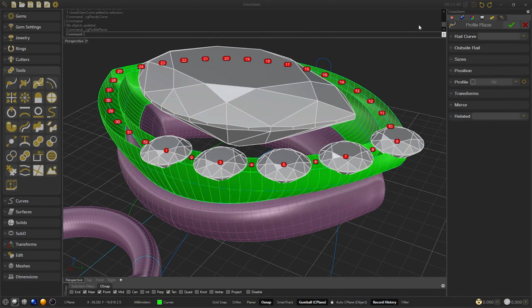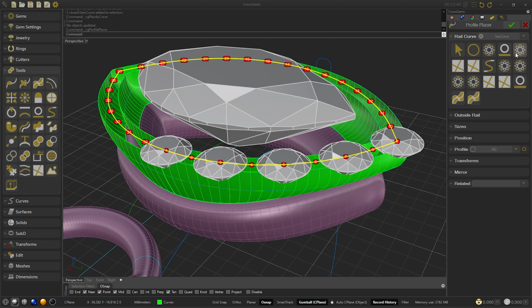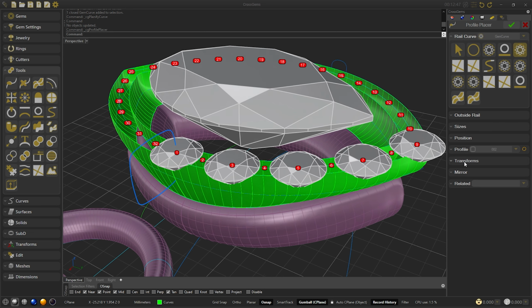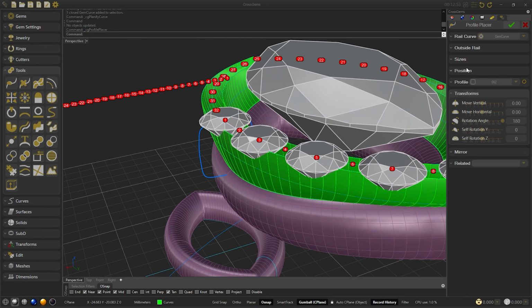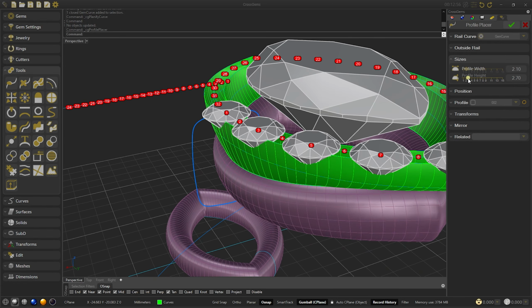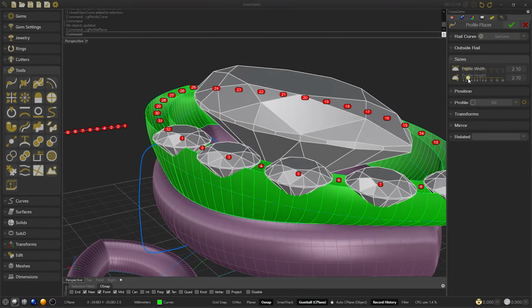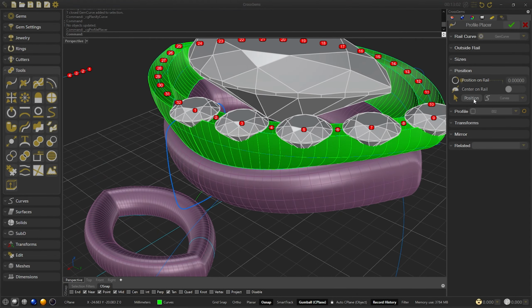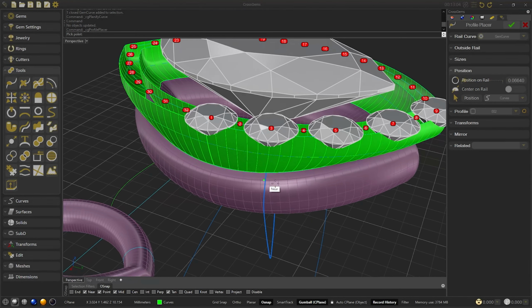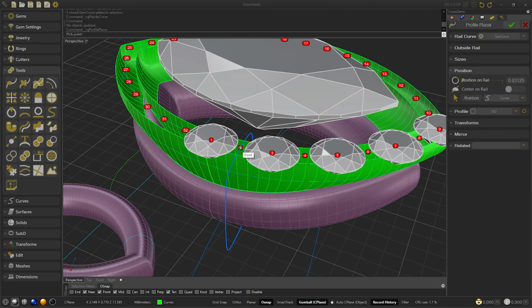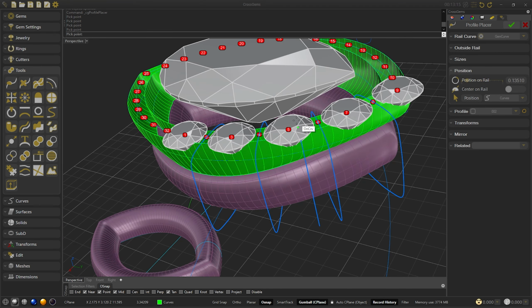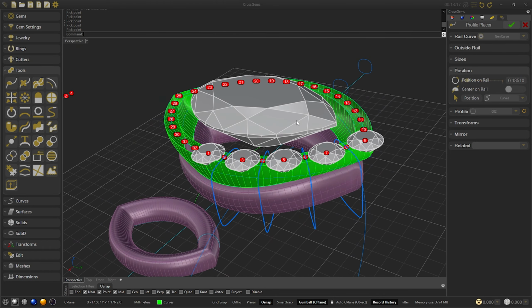Now create a profile placer, select the offset and rotate it to be underneath. We adjust the size to cover the entire loft, and now from options, go to position and with a snap enabled and points marked, press on these points. Once finished, press escape and confirm.